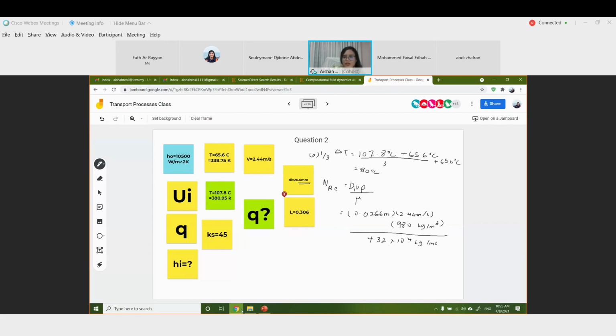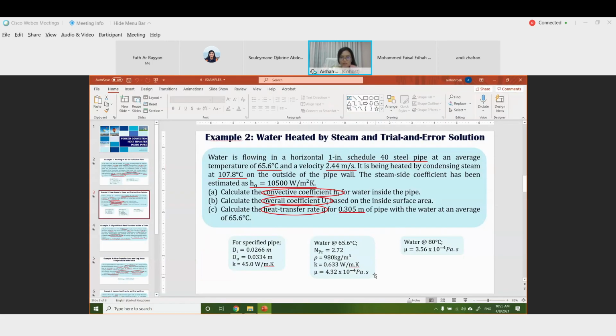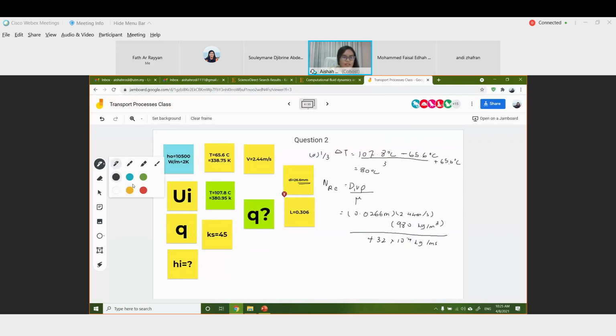Okay, so 4.32 is actually the viscosity at the entry temperature. Again, we can double check that we have all this correct by crossing out meter, meter, meter, and meter cube crosses out, then second and second, then kilogram and kilogram. Everything crosses out. So you can verify that you put in all the parameters with the correct dimensions. You don't need to convert it any further.